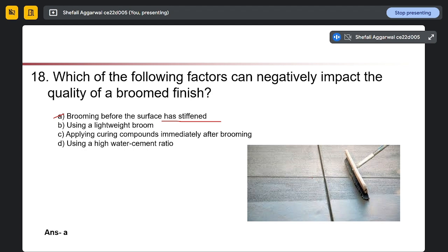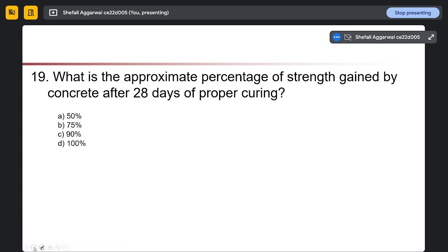So if we are using very thin aggregates, whenever load will be there, there are chances that the aggregates will break down. And elongated aggregates, if they are kept at a certain angle, there are chances that they will create a gap or hole inside the concrete system where there is no mix, a pore is formed.